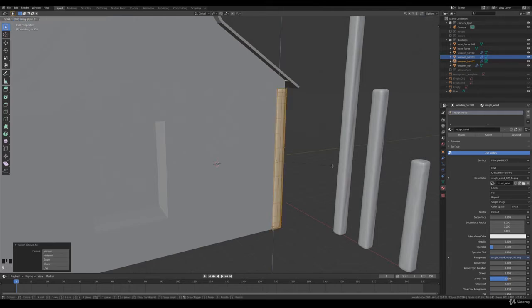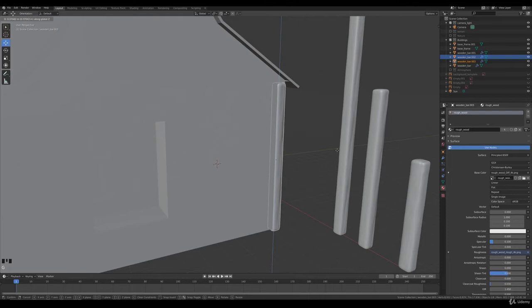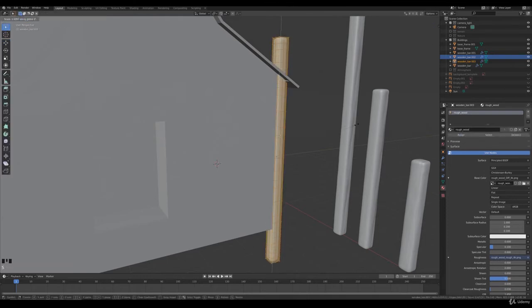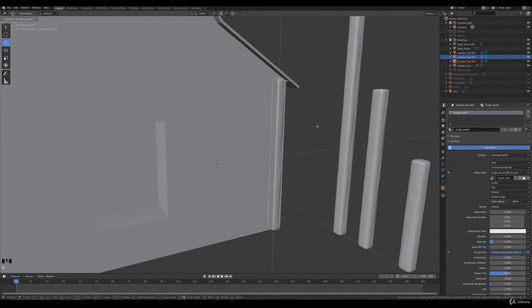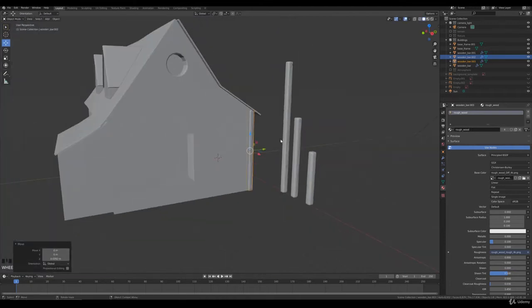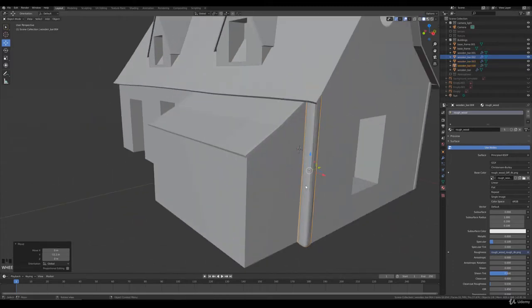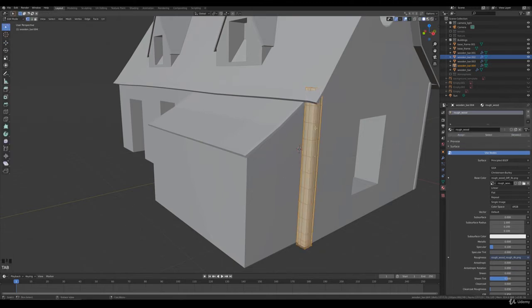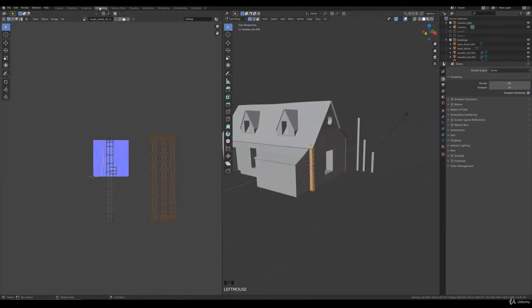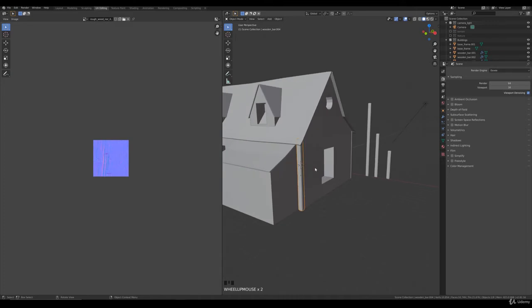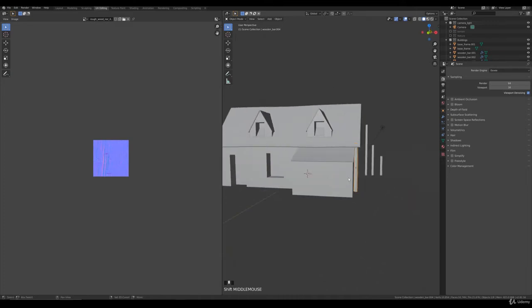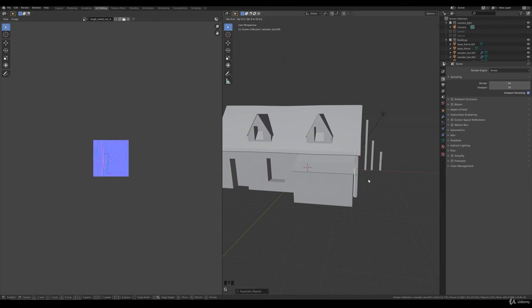And we have some space on the top, so go to the edit mode and you can scale it. As long as it is just small scaling, it doesn't really matter. But if you do it like this, you really have stretched UVs, and that looks a little bit ugly. So you go for a duplication, Shift D, G, Y. And what I like to do if I duplicate it, first we put this in position. I like to go to the UV editor, and we just move them so it looks different.